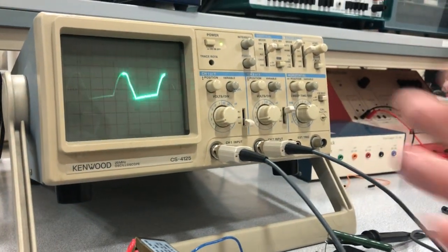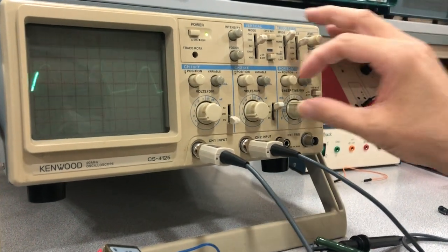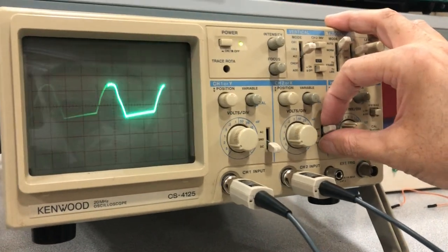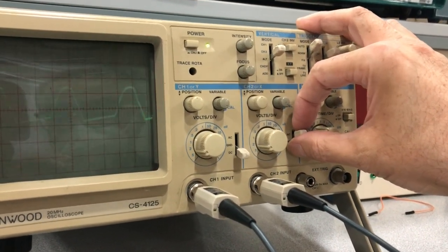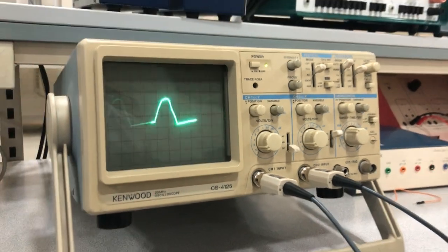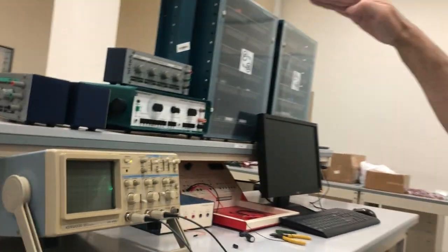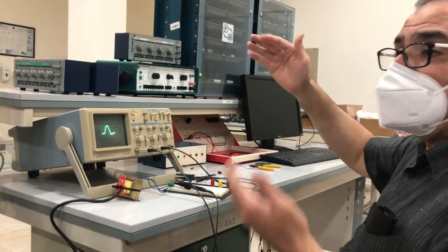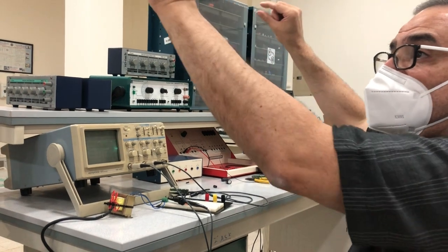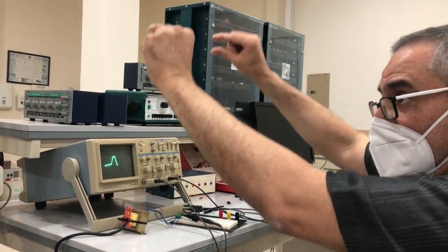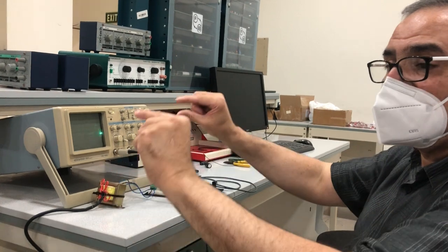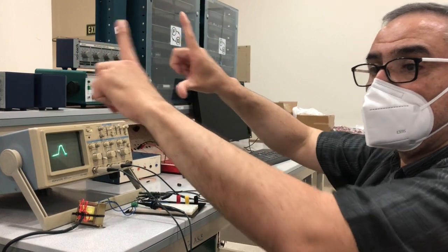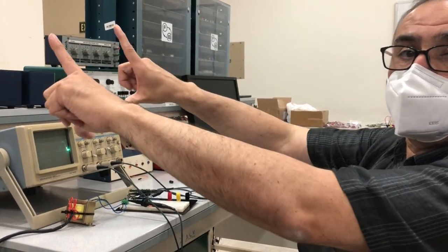Now, it doesn't help me here to go to AC. But if I'm measuring ripple, peak to peak, it might help me to go to AC and see only the AC on top of the DC. For example, I have a line average of 9 volts and it only goes up 0.5 and down minus 0.5. So I don't care about the 9, I want to measure the peak to peak ripple, meaning I only want to see the AC on top of DC. Let me cancel the DC and my AC signal will be brought down. This is not the purpose of it. Now I can go to a smaller subdivision and increase the ripple size on the screen and be able to measure it more exactly.